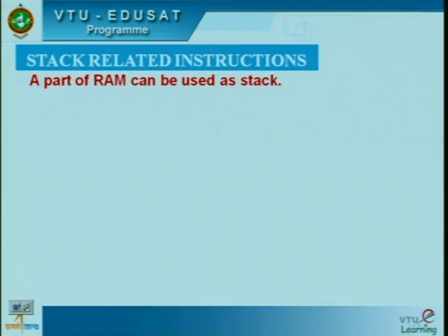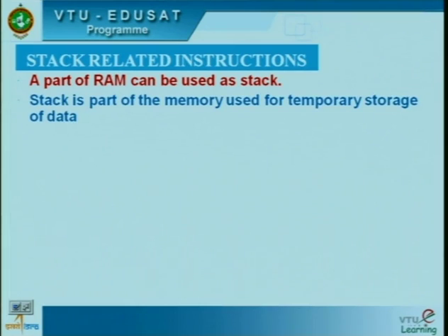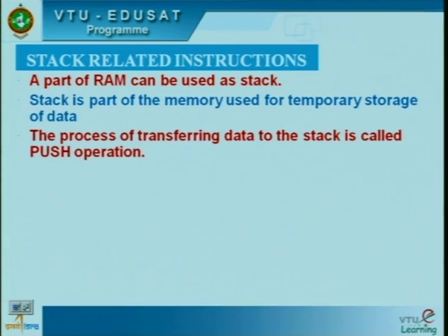You know that the stack is a LIFO structure. It is a set of memory locations which works in LIFO manner. Here we also have something called the stack segment, where the maximum size of the stack segment is 64 kilobytes. So a part of RAM will be considered as stack. Stack is part of the memory used for temporary storage of data.